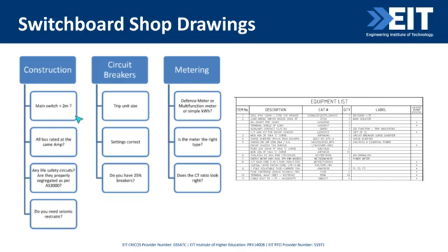So other things to keep an eye on is making sure the main switch height is low enough that it can be reached. So we say less than 2 meters. You want to check that your buses that make up your main switchboard all have enough current for what you need. You might have some location requirements. So if it's going somewhere that's earthquake prone, you might need restraints for earthquakes.